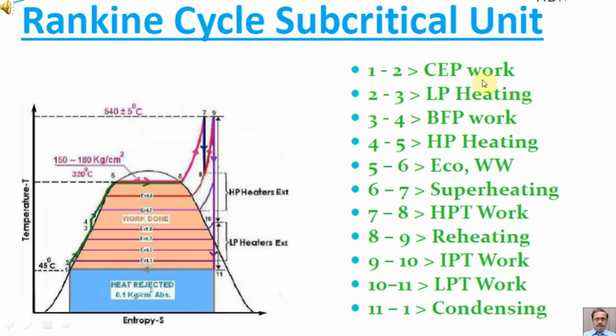From 2 to 3 is low pressure heating. 3 to 4 is boiler feed pump work. 4 to 5 is high pressure heating. 5 to 6 is economizer and water valve. 6 to 7 is superheating. 7 to 8 is HPT work. 8 to 9 is reheating. 9 to 10 is intermediate pressure turbine work. 10 to 11 is low pressure turbine work. 11 back to 1 is condensing.